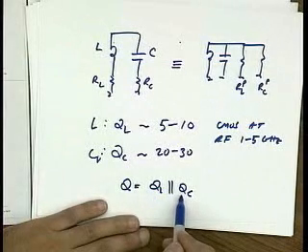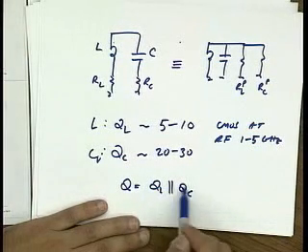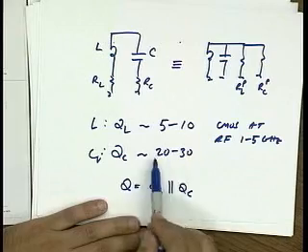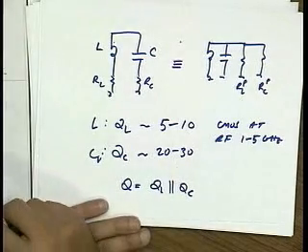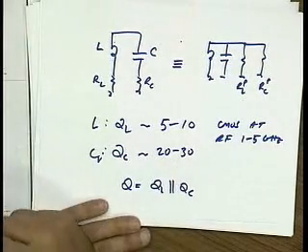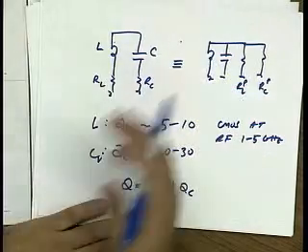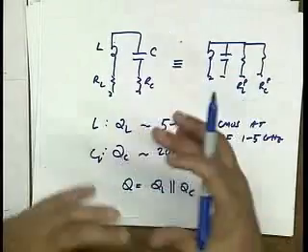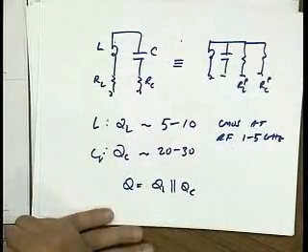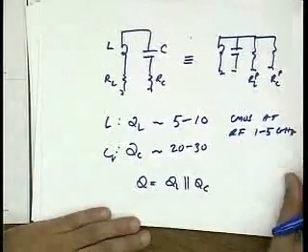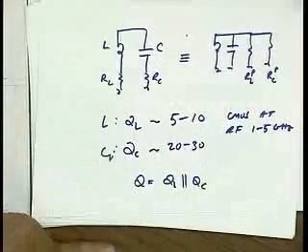If QL is much larger than QC, it will dominate. So you may be able to afford to only have a Q of, let's say, 15 on the varactor and still have a good tank. And so then you would choose an L basically large enough to hit that quality factor, and that would minimize the layout area. Okay? Or make the layout less awkward, let's say.